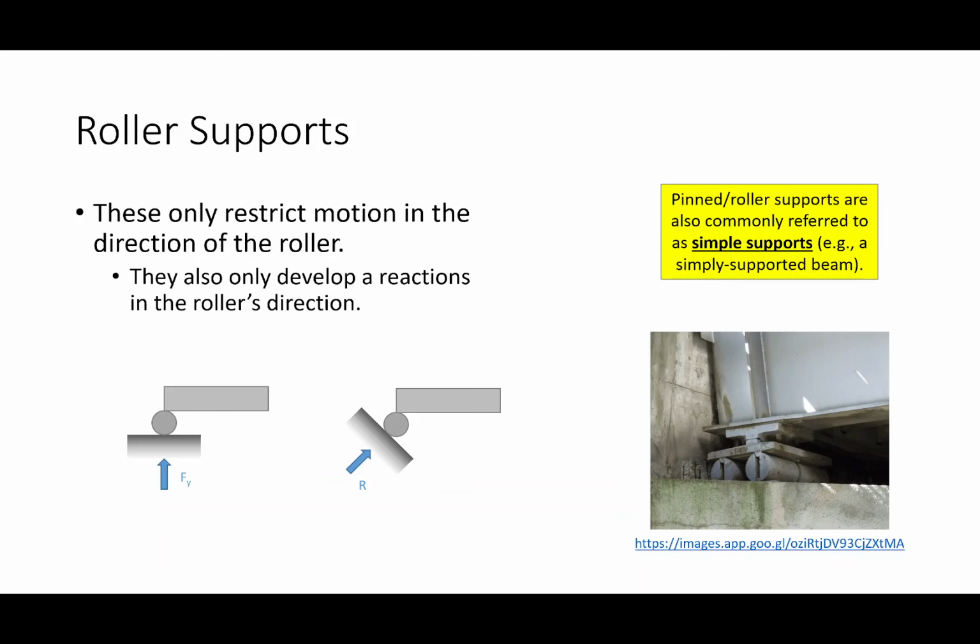So if we affix both sides and the temperature increases, that beam will want to expand and push the foundation and put a lot of force on that retaining wall. So we actually want to let the beam breathe a little bit so that it can withstand thermal expansion and contraction. Does that make sense? And I'm talking about this from a bridge standpoint, but you're going to find the same idea, for example, in mechanical system design. If you have an element that can expand and contract and it heats up too much, it might cause additional stresses on adjacent elements in the system. Same thing for you biomedical folks as well.